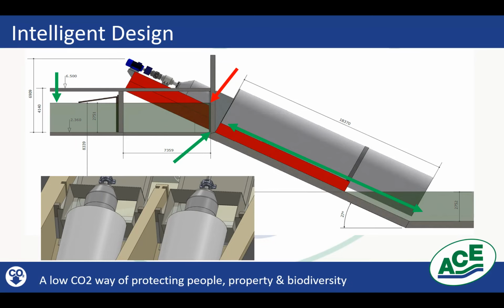Now, run back is something that's inherent with open trough Archimedean screws. You get a lot of water slipped back between the trough and the screw, which of course you need to pump up for a second time. So it reduces the efficiency. The other thing is, with an open trough, you can't pump into a head of water as a flood defense, because even if you put a brake to stop the product becoming a hydro turbine, water would still slip between the screw and the static trough. So you'd always lose water or let water back into your drain.